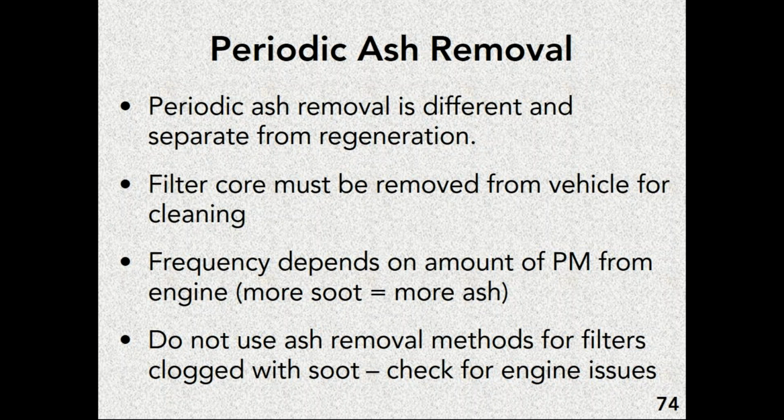By periodically cleaned out, I mean every truck that has a diesel particulate filter, whether it's a retrofit or OEM, every once in a while, the owner of that device has to take it to a shop that cleans filters, and they have to take the core out and clean it using devices that are recommended by the manufacturer to get the ash out. How often you do this depends on how much ash you collect.